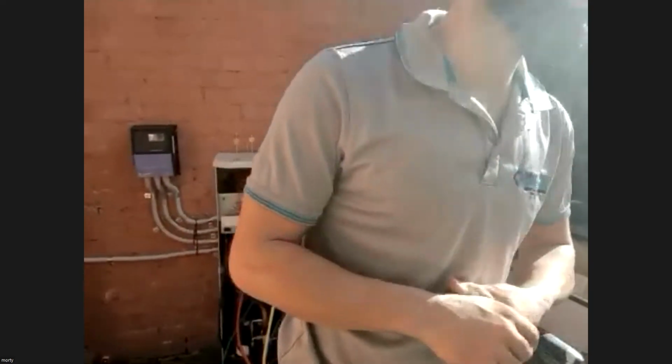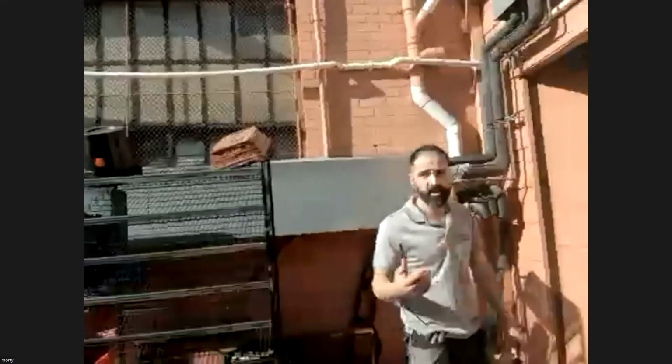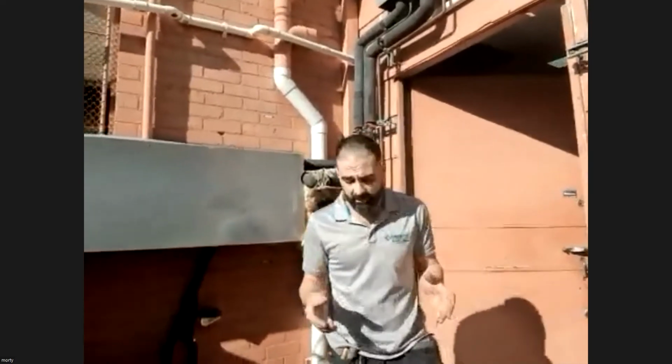You've got the measurements? All right, we're going to go inside again and have a look at the evaporator superheat. Since it's been running after defrost for about 10 minutes or so, we did have it at defrost earlier today, just to get maximum heat load into the evaporator during startup.